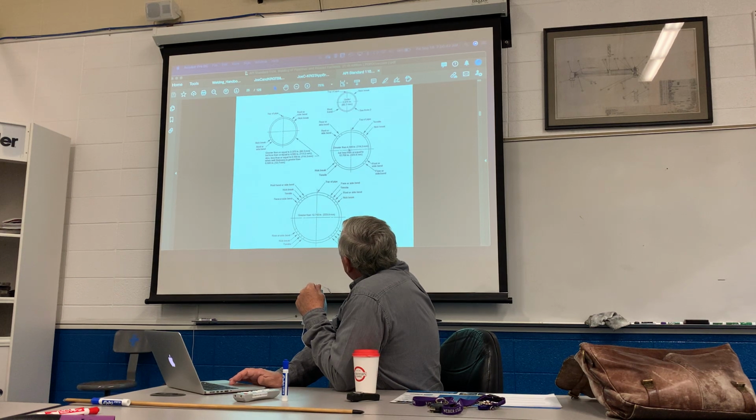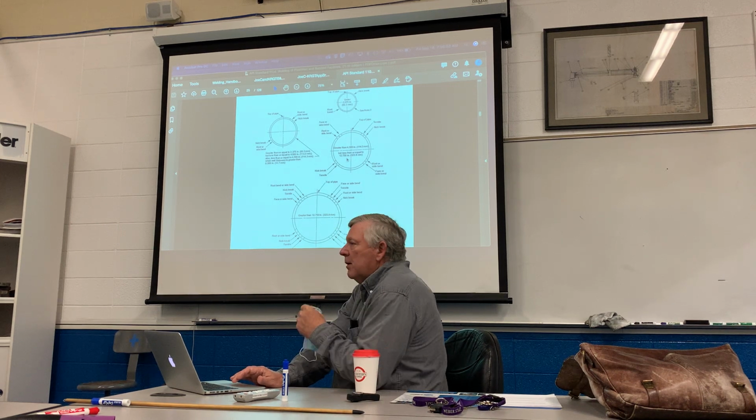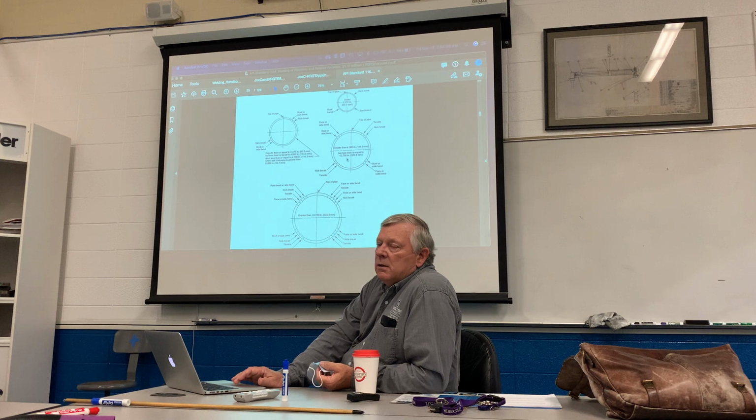This is for greater than 4 inch. Notice the diameter size there. That's 4 inches inside, so that's 4 inch pipe. It's 4.5 outside. Okay, but less than or equal to 750. I run into a lot of problems with this because I get on a job and I take a physical measurement of the 12-inch pipe and it's way bigger than 12.75. It's 12.9.